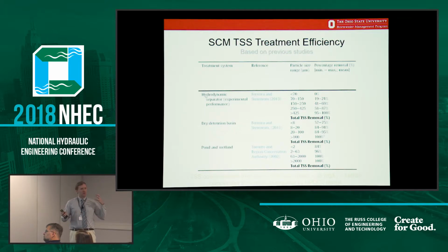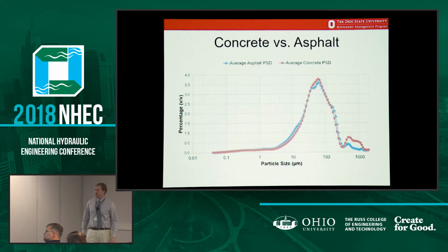So those of you who deal with percent removals versus effluent concentrations, getting 80% TSS removal when your influent concentration is 35 milligrams per liter is a big ask, folks. That means you've got to hit like 7 or 8 milligrams per liter as an effluent concentration. That's really tough. You're at some sort of filtration practice, if not a treatment train, to get there at that point. Okay, so those of you who work with regulators, that's something to think about. I'm not a fan of percent removal.